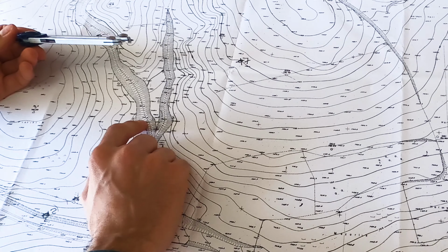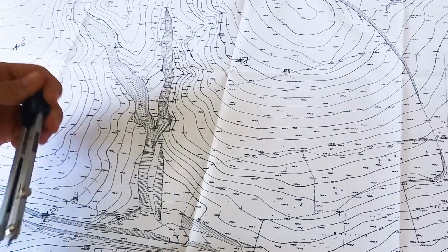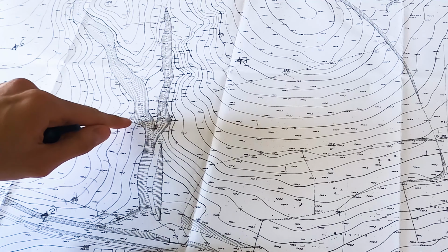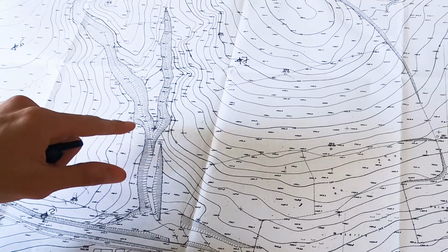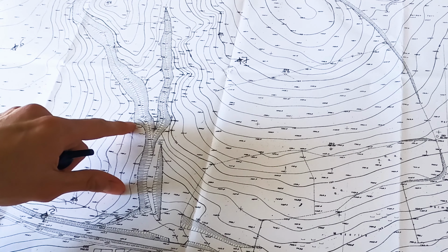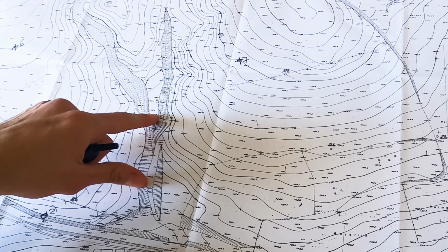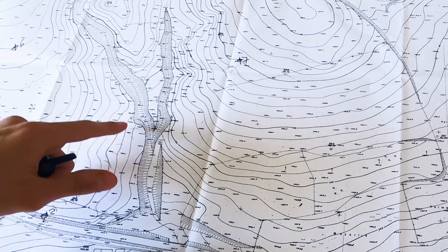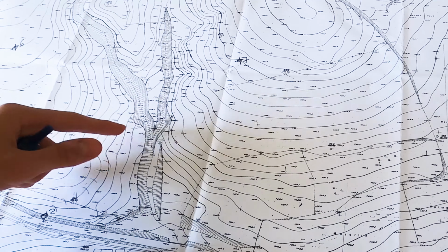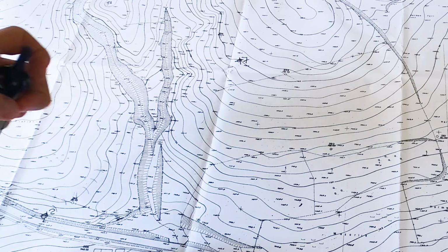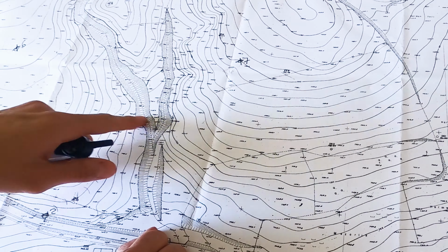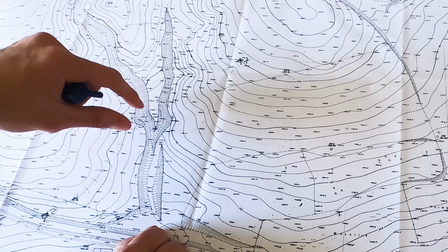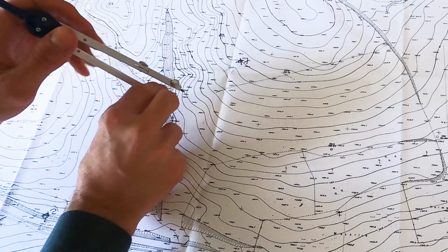For these regions in here, we have a difference in height, but a specific difference. The points are given. For example, 3 points are taken for the heights of the points in here. This one, for example, 748.5, 748. So in this case, we have to either cut or fill this region for the road to pass from here. There is no problem if we just cut the road from here directly, and then we can compute the fill or the cut in this region. Then we complete.